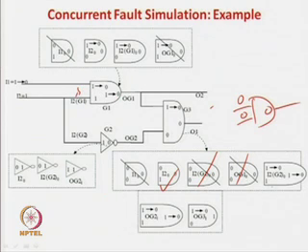Now you just think of the case I2 G2 stuck at 0. So this one is stuck at 0, if you think, then what happens? Then this one will be 0, so this one will be a 1, and here there will be a change from 0 to 1, because initially the pattern applied was a 1 over here. Okay, so the pattern one was applied, 1 over here, and if there is a stuck at 0 fault here, there is no effect over here. So it was 1 1, the output was a 1. So your gate was looking like 1 1 and the output was a 1. So this was the old computation.